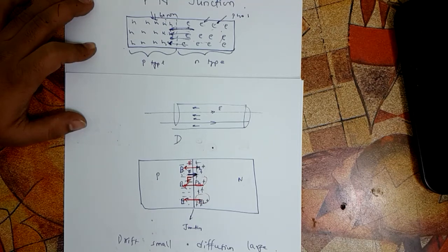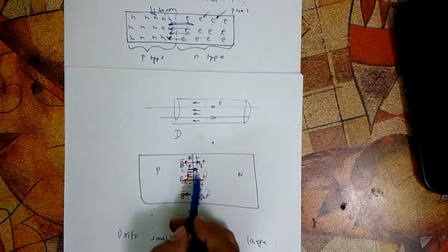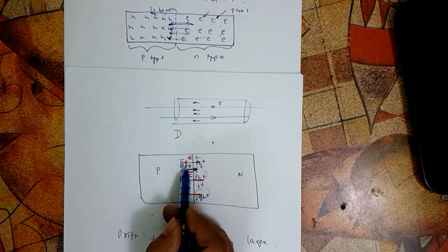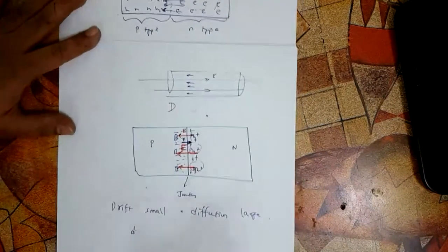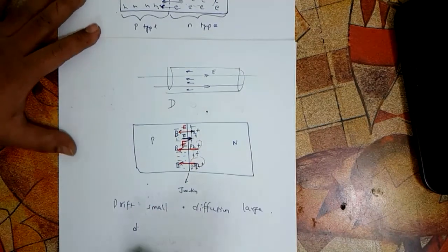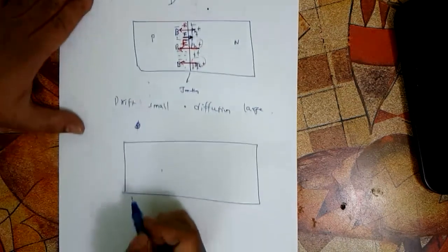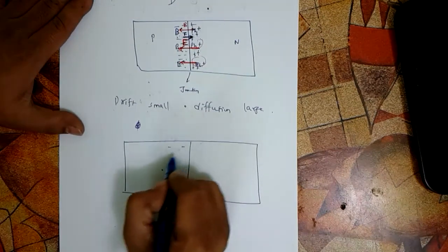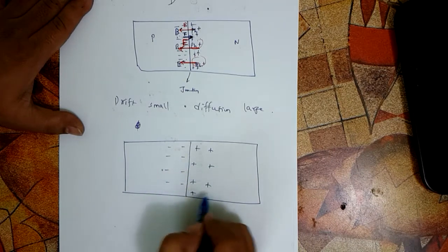And we say that this is something like a steady state. So the number of electrons coming towards left is equal to the number of electrons coming towards right. So there is no net motion, isn't it? And now that there is no net motion, whatever electrons have come here, that's all fine, and whatever electrons have left here, that's all fine. So what we have created in a steady state, or in equilibrium, is a region of negative charges here of boron and positive charges here of phosphorus.